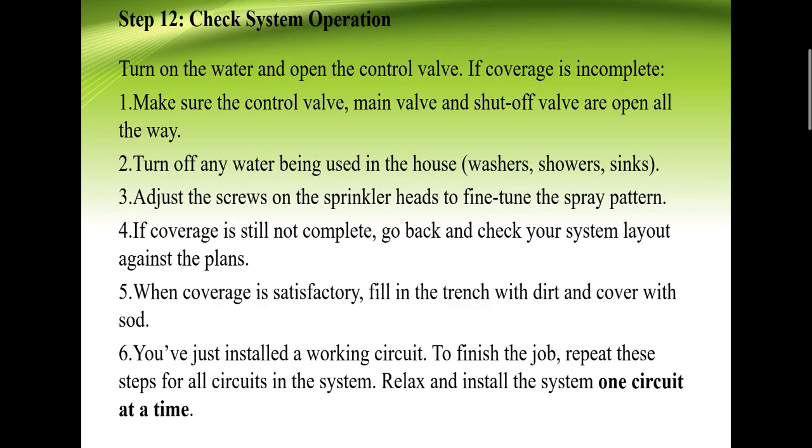For the last step, check system operation. Turn on the water and open the control valve to see if coverage is complete. Make sure the control valve, main valve, and shut-off valve are open all the way. Turn off any water being used in the house: washers, showers, sinks.